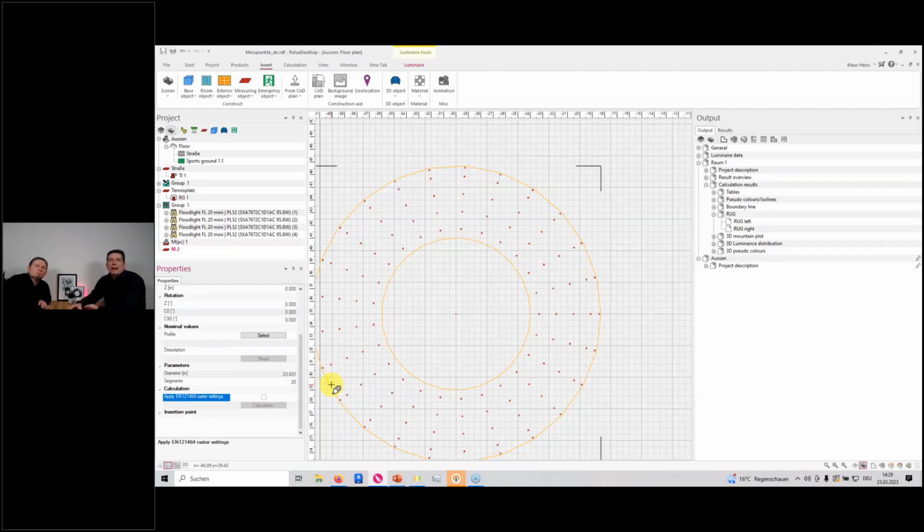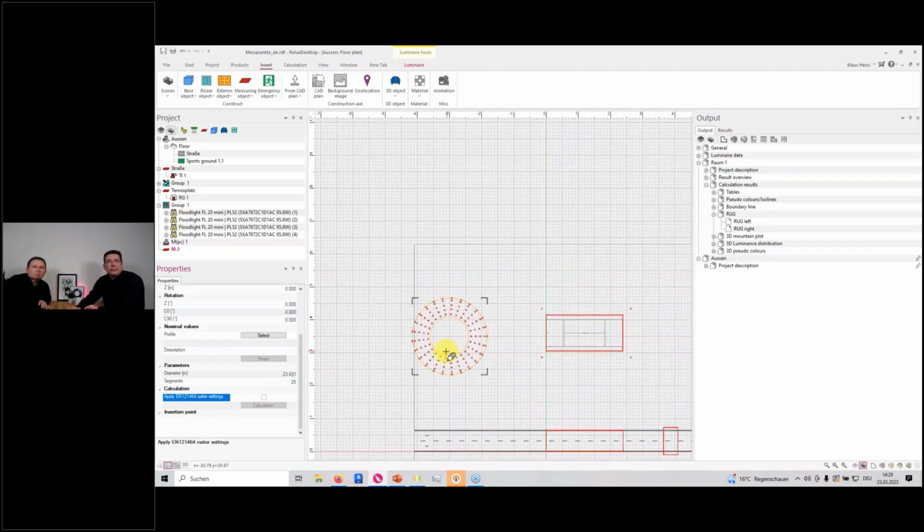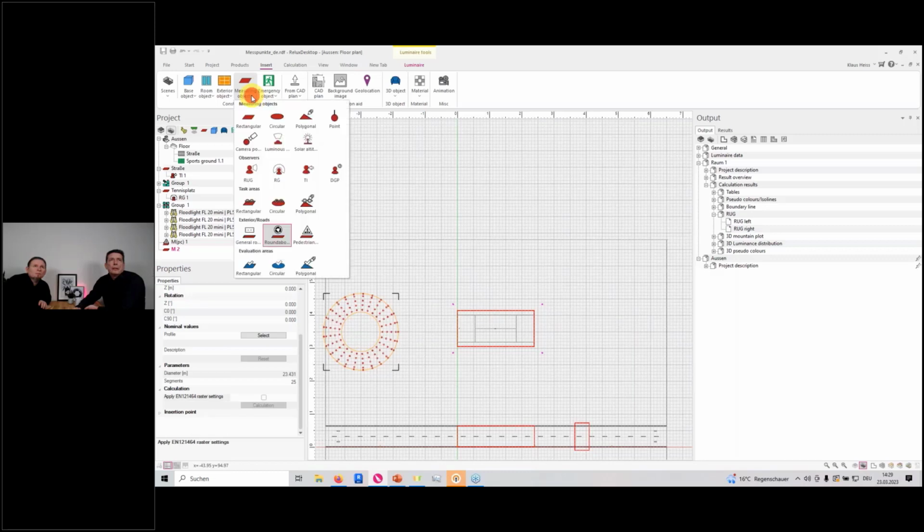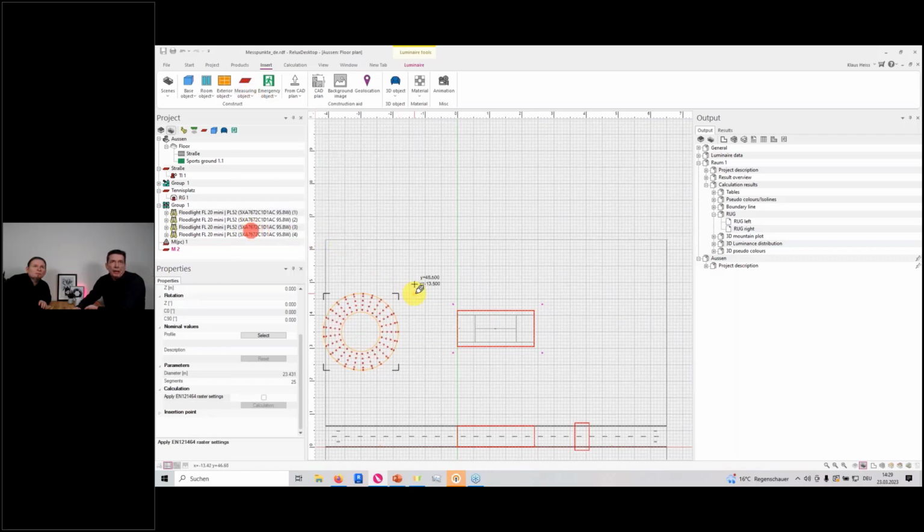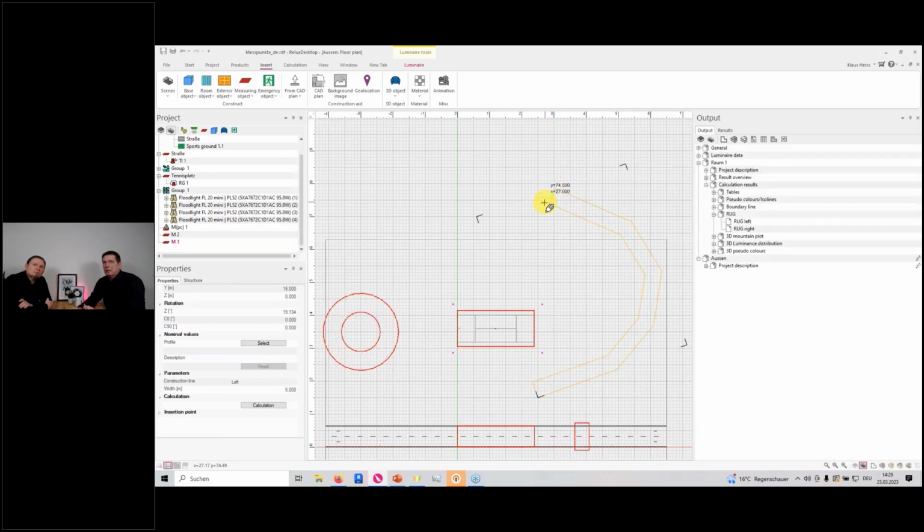Okay, and the last one I want to show is the general road. The general road can also be used in interior scenes. The interesting thing here is that you create this surface not by drawing a shape, but by drawing a line. In this example, you can simulate, for example, a curve. At the last point, press Enter, and then you can give the width of this line.